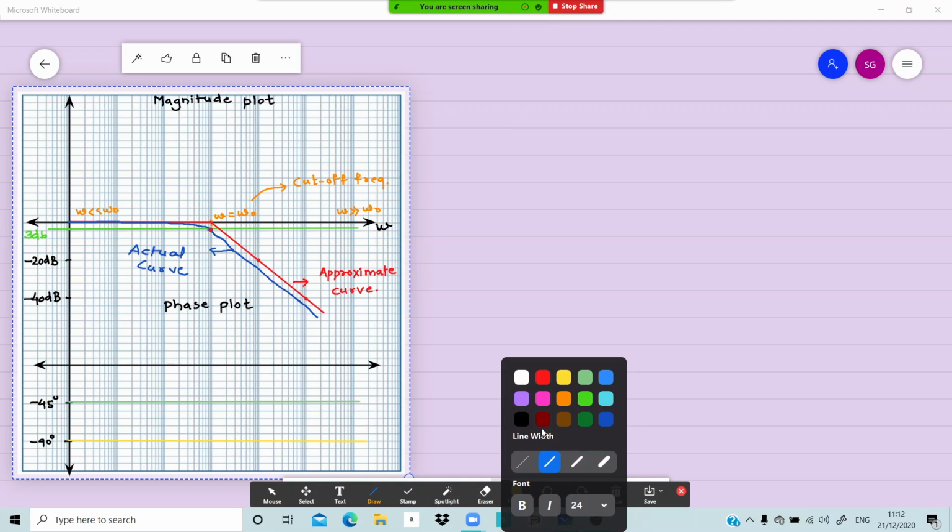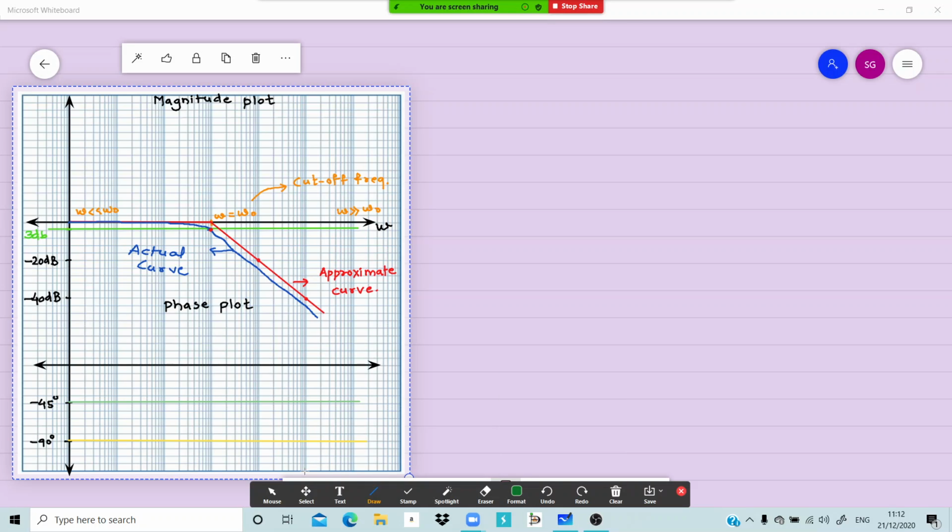Okay, so how is it going to vary? Again, I am drawing with blue or green. Okay, see now. Initially it is 0. At omega equal to omega naught, it is going to be 45, and then again it will go along 0. So as if a reversed S you are going to have. Yeah, very good. This will be the curve for phase, right? Yeah, I should write over here. This is omega. So we have done with a single real pole.